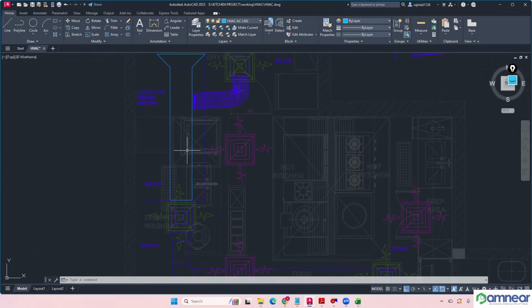There also I need to consider the acoustic lining. So better you can provide there, because actually we don't want 400 by 350 there, and this diffuser is located very near. It is not a huge issue. Even if we are extending up to here, that is totally fine, no problem.